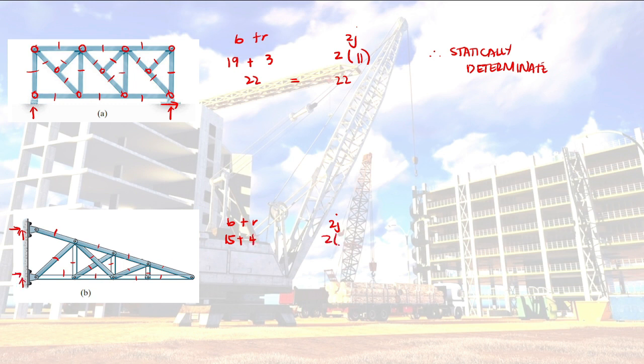Then 2 times how many joints? 1, 2, 3, 4, 5, 6, 7, 8, 9. 9 joints. So 15 plus 4, that is 19. Then 2 times 9, that is 18. So it is greater than. Therefore, it is statically indeterminate.